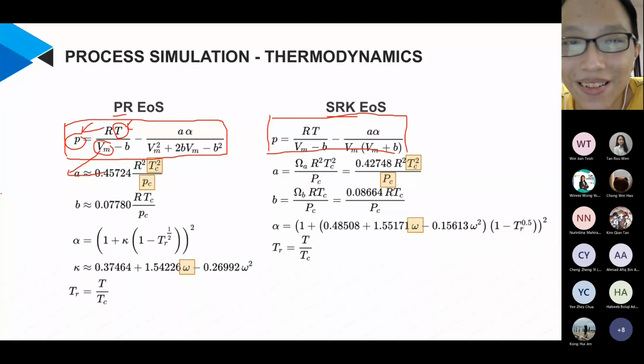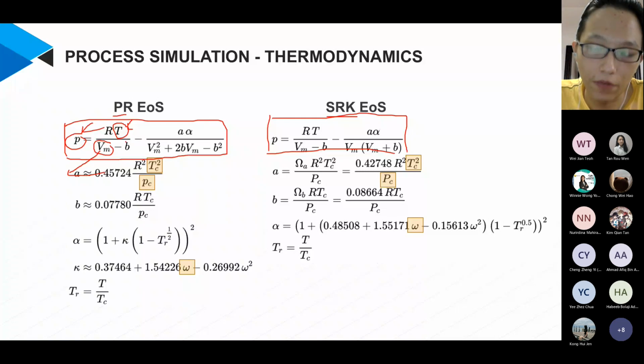That's why we need a process simulator to solve the model. So why do we need the volume? Because with the pressure, temperature, and volume, these three, we can choose two to provide, and the third will be calculated by the simulator. And from these three properties, we can calculate everything else. We can calculate enthalpy, entropy, density, viscosity, heat transfer, work done, and so on.